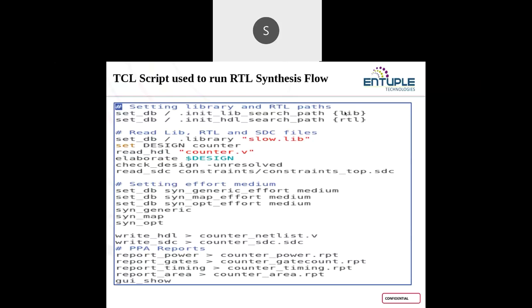You can go to that technology node, whichever it might be, 45 or 90, and set based on that. Once after setting that, whatever area report or power report you generate, or even if you are checking the timing, all these things will be generated based on the library you are making use of. So from that particular library you'll be able to see all these reports. Area information, power information, all these things will be taken from the technology node which I am making use of.